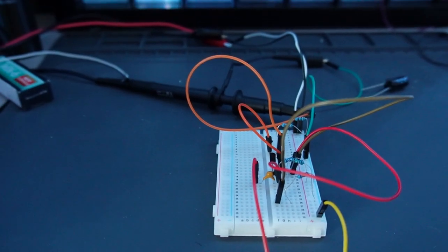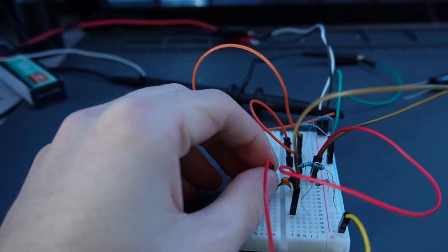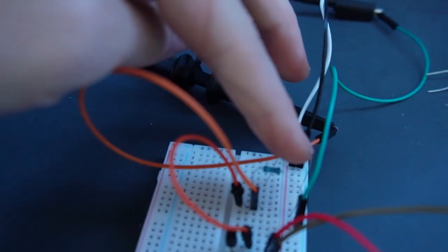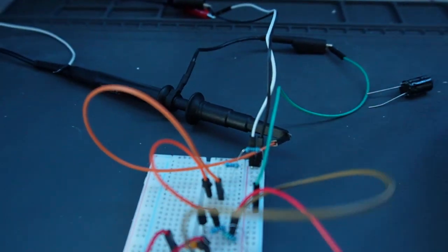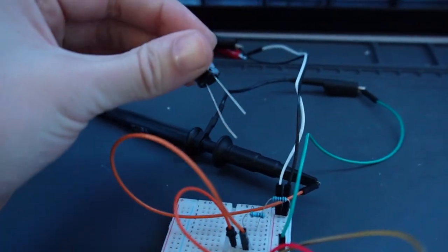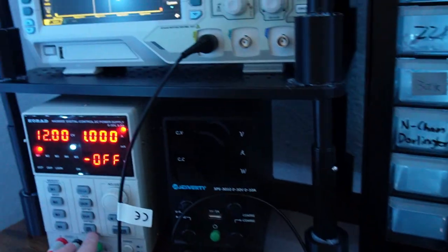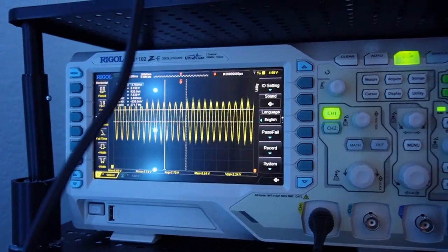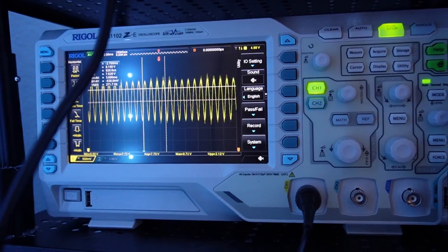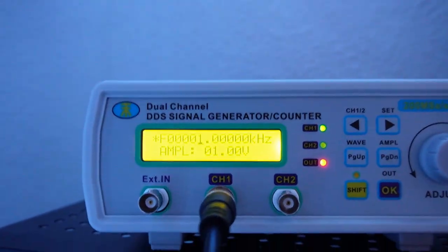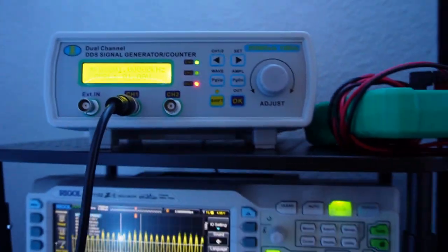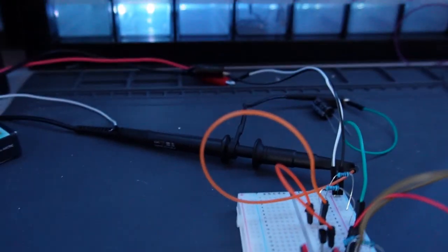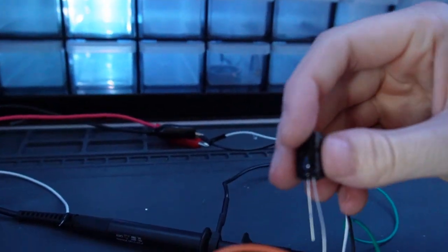So this is the modified circuit. I have an input signal coming in via a capacitor, and I actually have the load over here, but it's currently disconnected. When I want to reconnect it, I will use this capacitor here. So when I turn on the power, right now it's measuring what's at the collector terminal. And we're seeing around 2 volts peak to peak, which is pretty accurate with our signal gen, which is doing 1 volt swings. And so it's currently just taking the full signal. And now if I were to connect the capacitor,